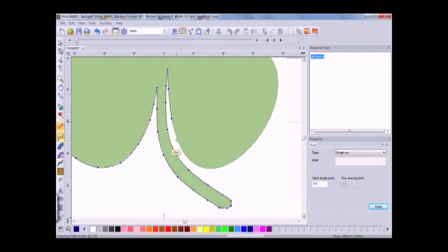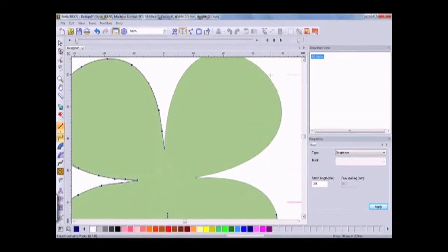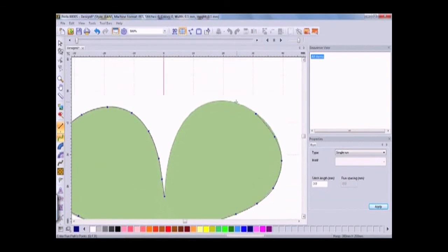Two straights, and again I'm going to my control key and I'm putting down my curve points. I'm going to pan and get the area of the screen that I want to digitize on, and continue to hold the control key down, straight point, going back to curves, and I'll continue all the way around the outline of this design until I get back to where I started.